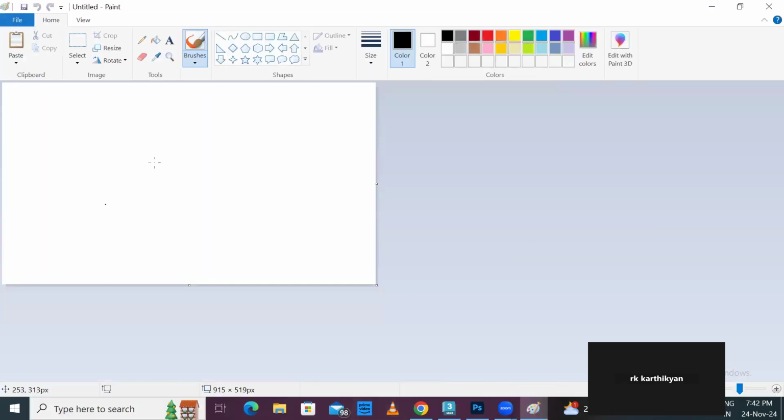Okay, normals is an imaginary line which is projected outside of the surface. So think that this is a surface and the line will draw something like this. This is the outside of the surface. On each and every polygon face, the line will face a particular direction. So this direction is called the normals. So this direction should face outside.